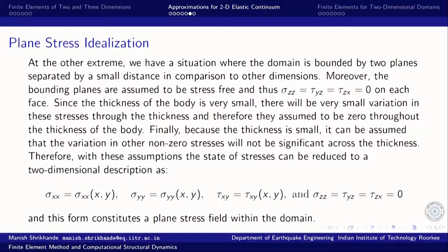but that can be derived: knowing the stress and strains in xy plane, we can find out what is epsilon zz. So, at the other extreme we have a situation where the domain is bounded by 2 planes separated by a small distance. We will see what it means. The bounding planes that are there are assumed to be stress free and the loading is in plane, right.